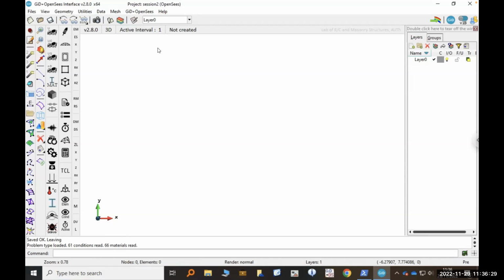So the first thing I'm going to do is start building a model, right? And again, this is a very simple linear model, a bunch of lines. So I will click the line command, and I want my first point to be at 0, 0, 0. Great. I want my next point to be at 0, 0, and let's give it a height of 3.5.